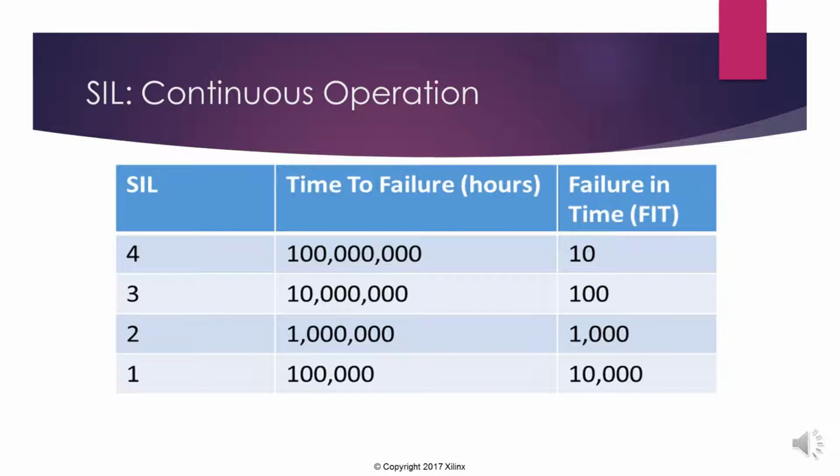Now just to give you some context, a modern FPGA may be around that number of 10 FITs, maybe slightly lower depending upon the process node, maybe slightly higher depending upon the node as well, but it will be around that number. But that doesn't include the oscillator, the power supplies to power it, the board that it's connected on, the solder joints, or the system. So the actual system would have a failure rate much higher than that.